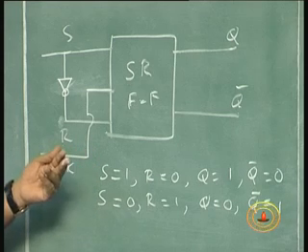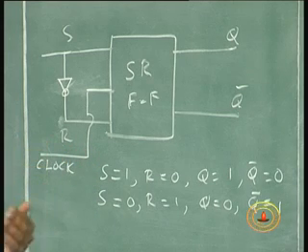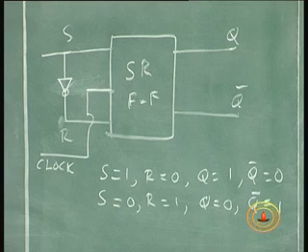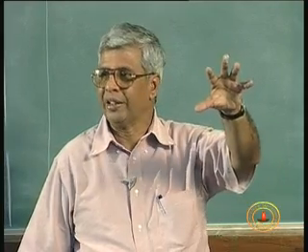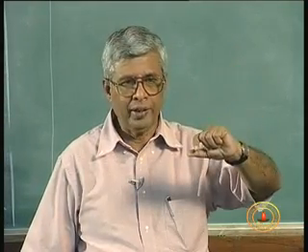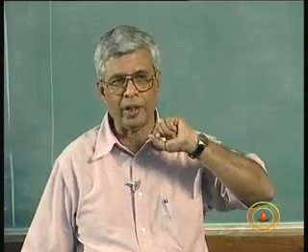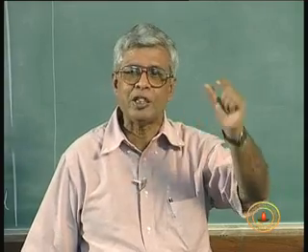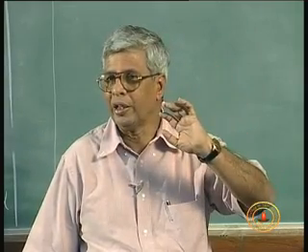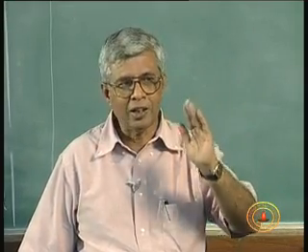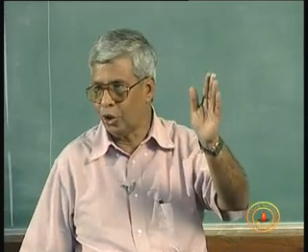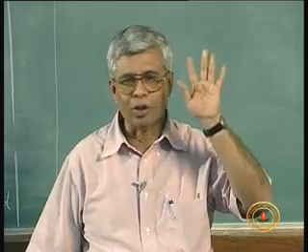operation. For a memory operation, earlier we had to put a 0 0 for memory. Once I put an input 1 0, then remove it and put 0 0 for memory, or put a 0 1 and remove it, put 0 0 for memory. Now there is no need to put a separate 0 0 for memory. If you give a clock, the input gets stored. If you remove the clock, the input remains stored.